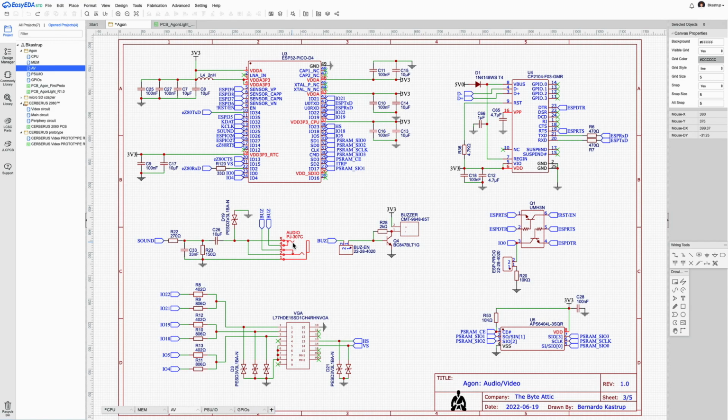Now, the way this is constructed is that if there is no plug inserted into this connector, then this line is connected to this line here, which goes there. The same for this line. If there is no plug inserted, then this line here will go this way to buzz, which is again the buzzer signal. So the buzzer will buzz if there is no connector inserted in the audio jack, but if a connector is inserted, then this connection here is broken, because these little connection points will be stretched down in this case, and this one will be stretched up, and this connection point will go open, and there will be no signal to the buzzer. So when you connect speakers to Agon light, the buzzer goes silent. And if you disconnect the speaker, the buzzer will produce the sounds, except if you remove this shunt on this header, and then you silence the buzzer under all circumstances.